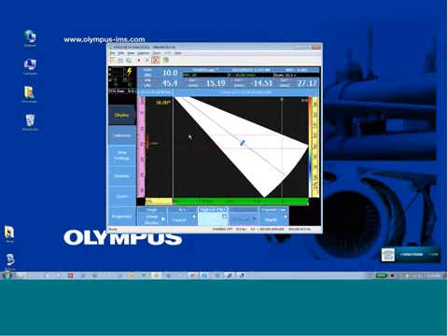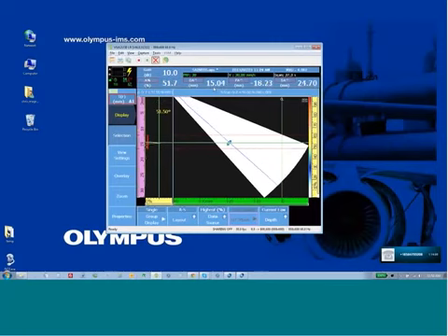If you can maintain the signal at the correct depth, and in this case it's 15 millimeters, across the entire sector scan prior to calibration, this right away is an indication that the velocity of the wedge, the velocity of the component, the probe and wedge parameters such as pitch, height, wedge velocity, wedge angle, are all correct.